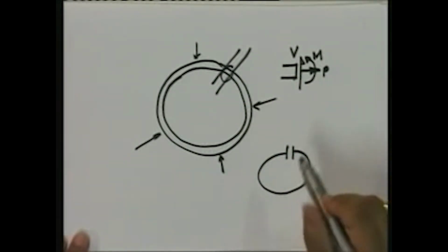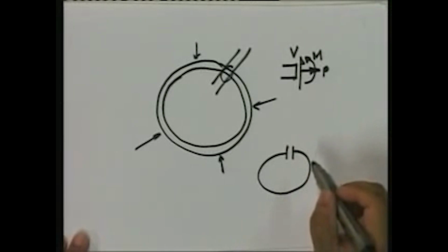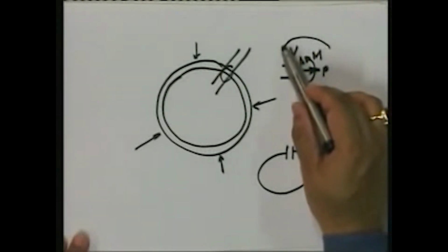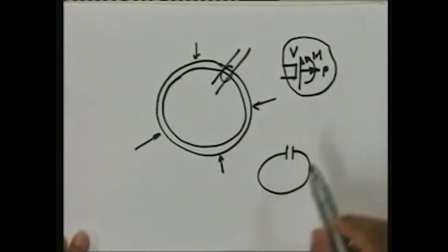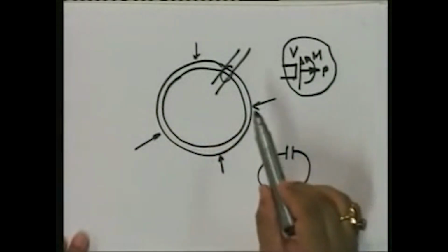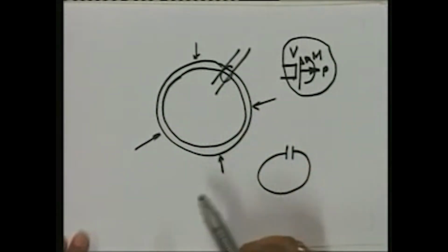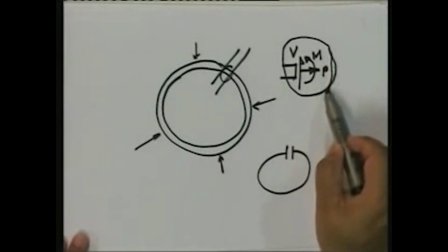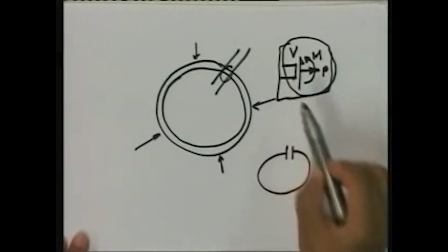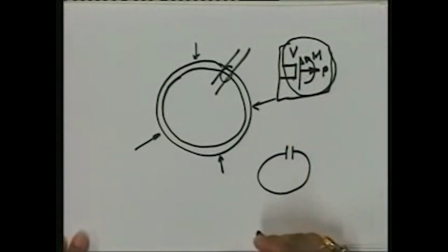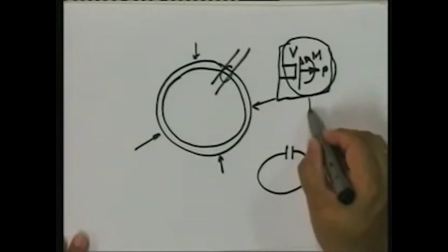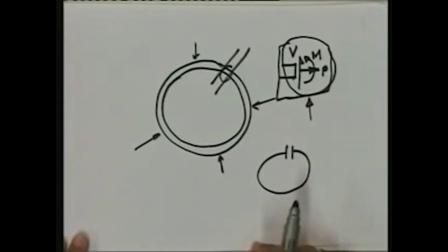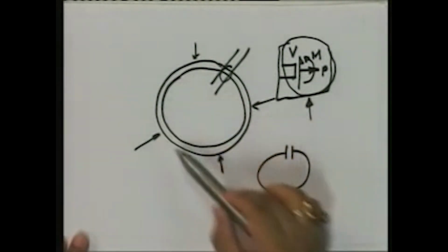In other words, these are my internal forces developed at a cut. And note this, that in this particular problem, when I make this cut and I generate these three, can I find them out? Think about it. I can't. These three are unknowns which I cannot find using any equilibrium equation.